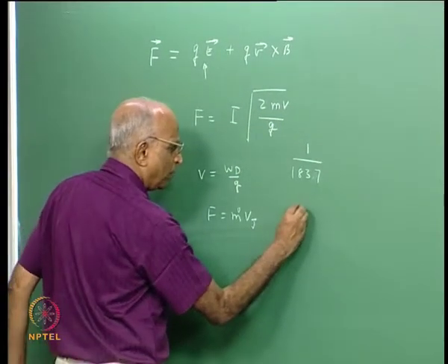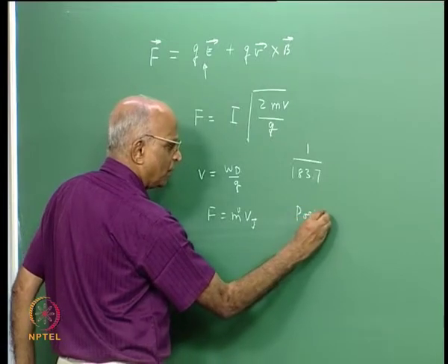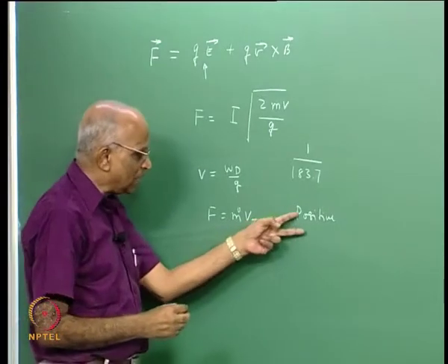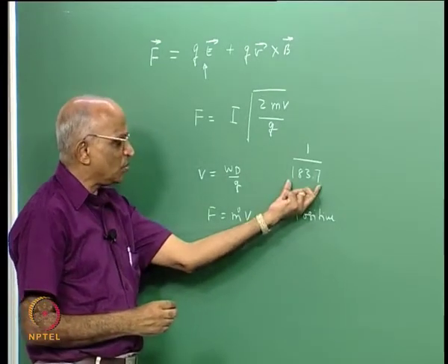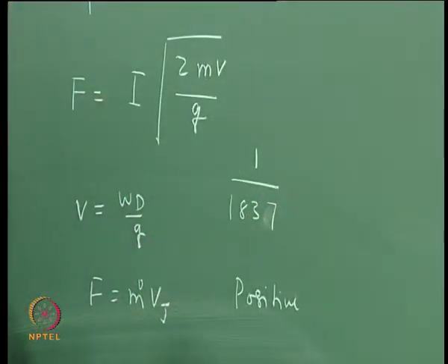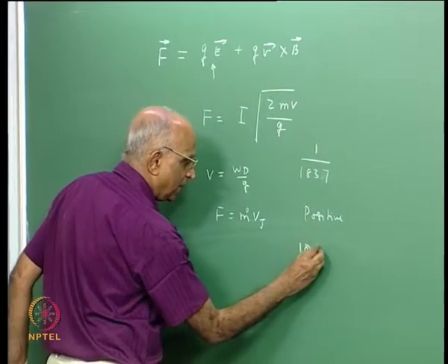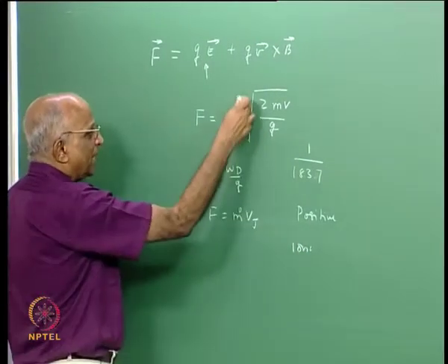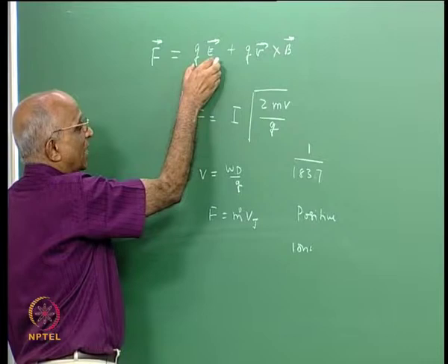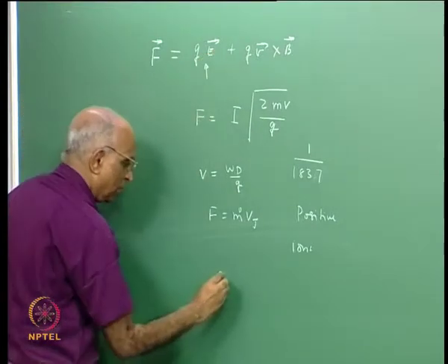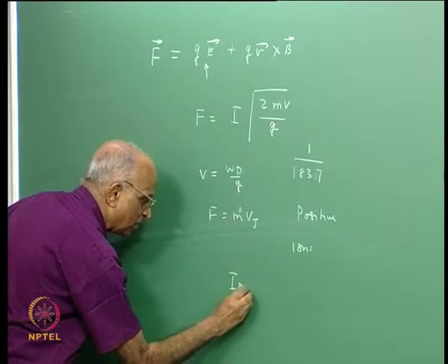Normally positive charges are used for generating the forces, and we cannot use the electrons because their mass is so small that I do not get any impulse at all. Therefore these positive charges are what are called ions, and such a mechanism of using electrostatics, namely an electrical field, for generating a force is also known as ion propulsion.